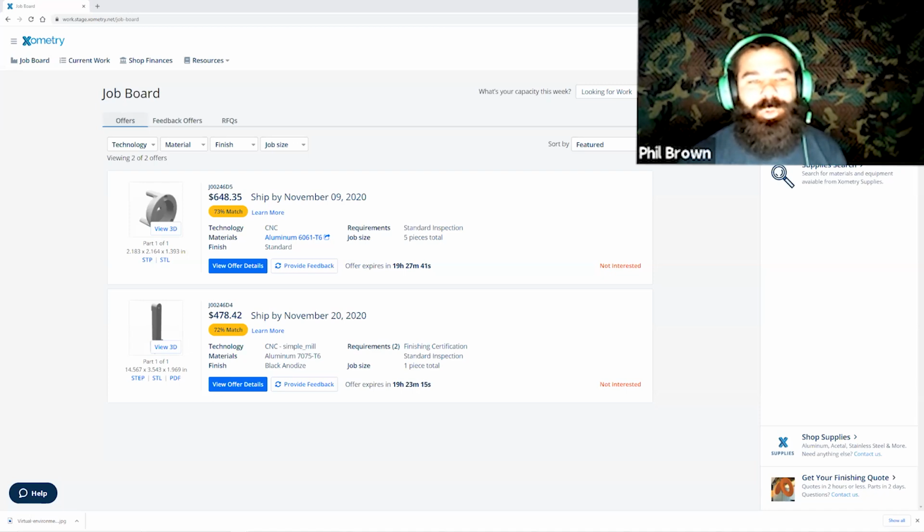So depending on who you work with, your finishing can really make a big difference. I also know that a lot of parts that I did, we would avoid anodizing on, and I'm not saying anything bad about it. It's that if you get anodized parts from multiple different suppliers, the anodizing coating can be dramatically different in shades. Is that correct, Greg?